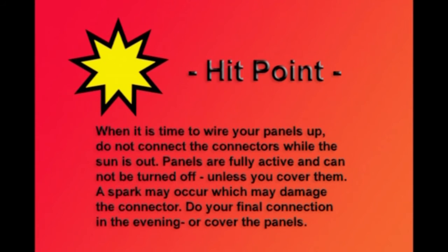When it's time to wire up your panels, do not connect the connectors between the panels while the sun is out. Panels are fully active and cannot be turned off unless you cover them up. So a little spark may occur which may damage the connector. So do your final connections in the evening or cover up the panels.